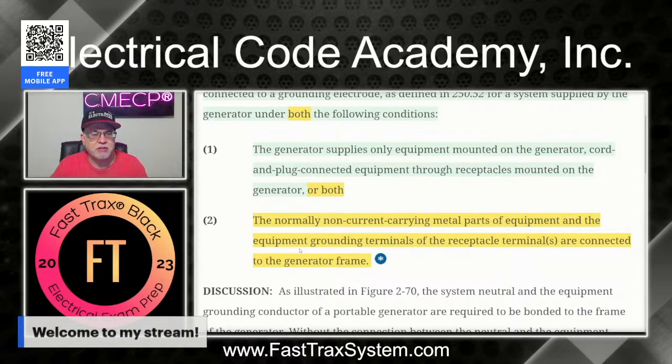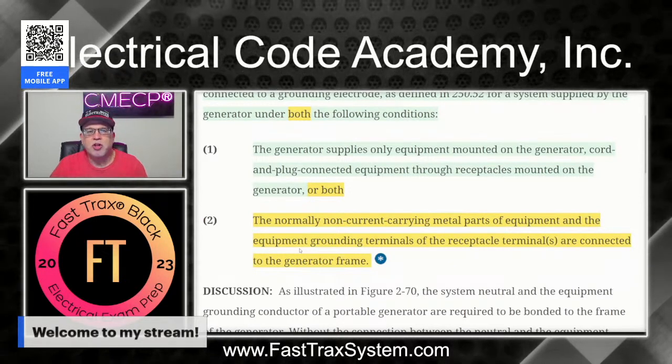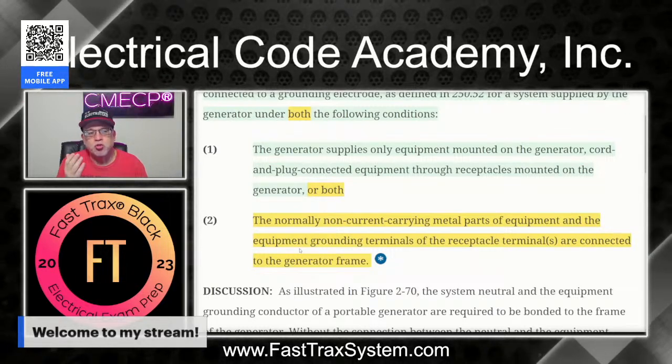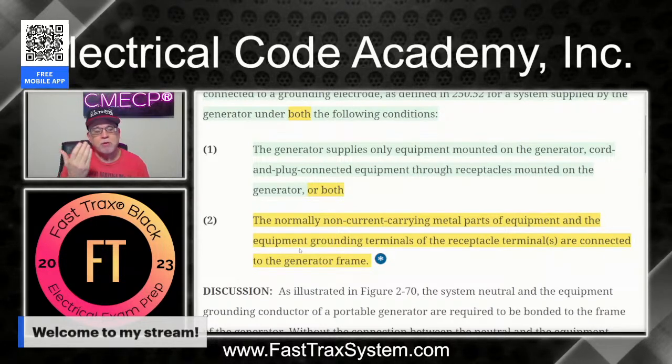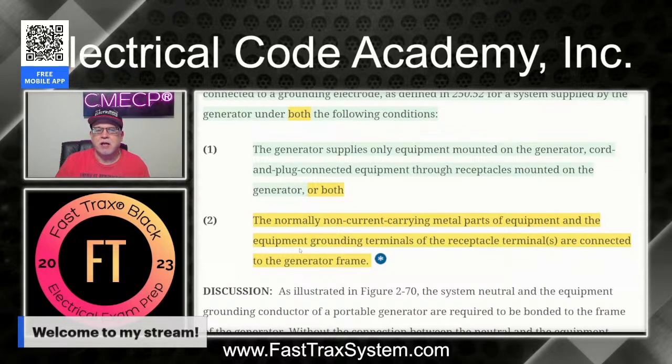For the equipment grounding terminals on the receptacles, all connected together. And ultimately, it's going to connect back to the grounded point or the neutral point on the actual generator. Okay, so this is what we refer to as a bonded generator.